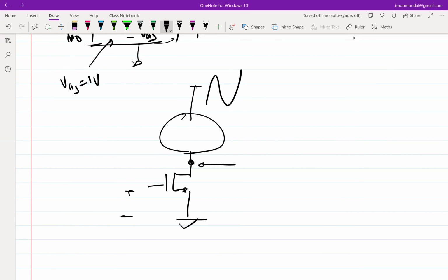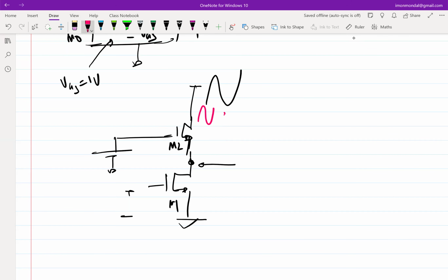Yes, and so essentially the common gate configuration that we did before the break helped us in achieving that, right? So if we have, assuming this guy is also biased in saturation, the amount of swing here, if this is delta V naught, is approximately delta V naught divided by the intrinsic gain of M2, right?